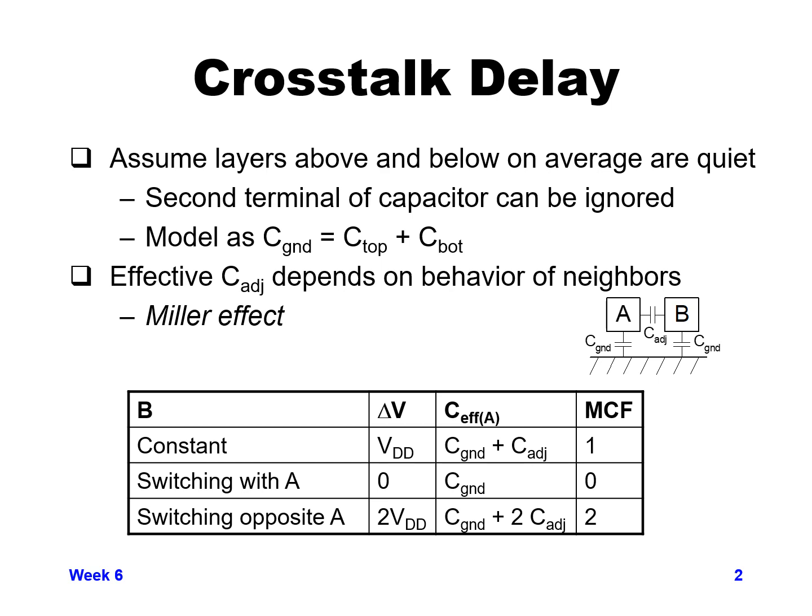And so you can see that, depending on what values of signals are next to each other and which direction they're switching at the same time, they could either help each other or hurt each other, and your max delay and min delay will have a large variation depending on which direction the signals are toggling.